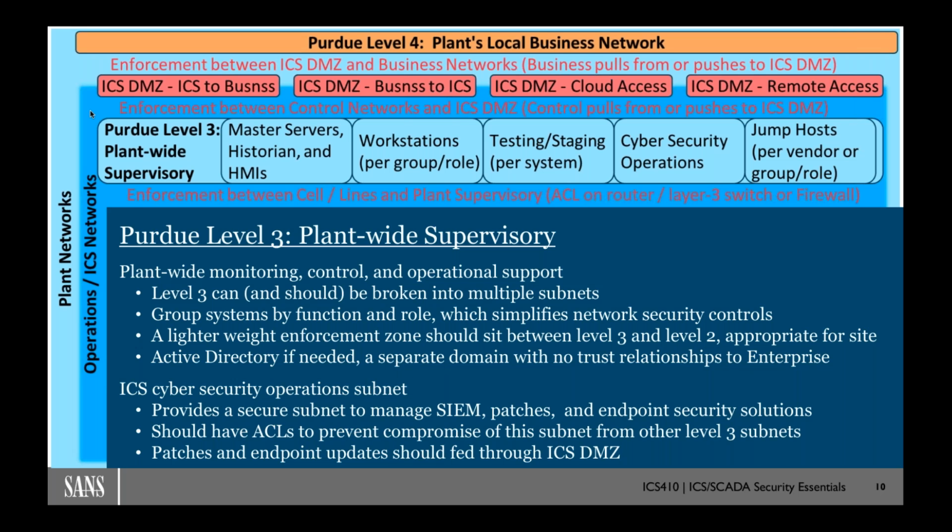If you have a networking enterprise team that does all the routers and the switches, say you have 20 people that do enterprise networking, I do recommend taking 3 or 4 or 5 people from that enterprise team and making them the dedicated resources for industrial control networks. So they may be part of the larger team and share the same technologies and resources, maybe even the same management, but those individuals, right, are the only individuals that deal with networking inside of the control networks themselves.